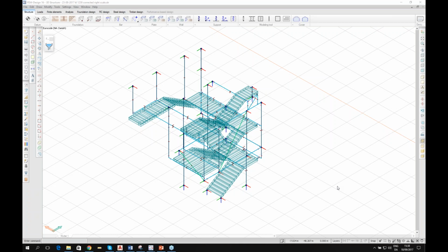Matthias is asking, I was thinking about your last example. There's eccentricity in the center points of your beam elements in the drawing, but in FEM-Design they are connected. What we did in this model, the only thing we really modeled from the CAD drawing is all the steps and the plateaus. The columns are just connected upon the model afterwards. They're just drawn as bar elements, not as shell elements. So we just modeled that after the geometry, without snapping to the lines on the CAD drawing.